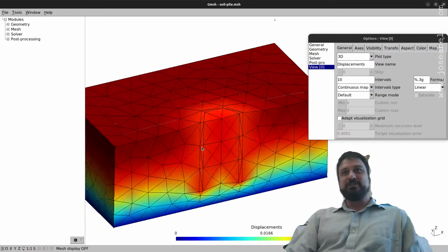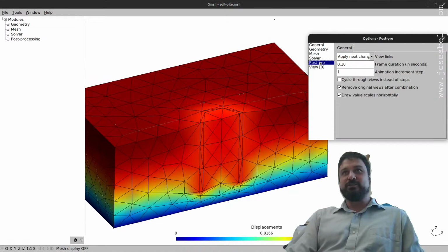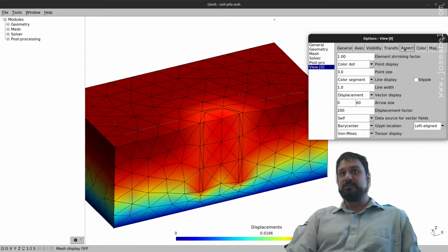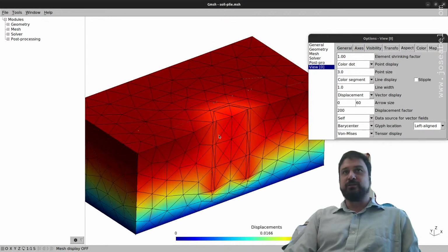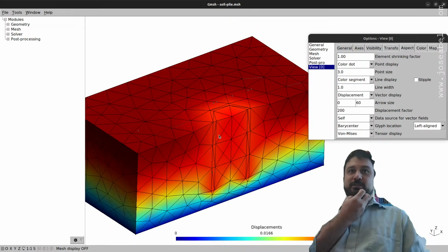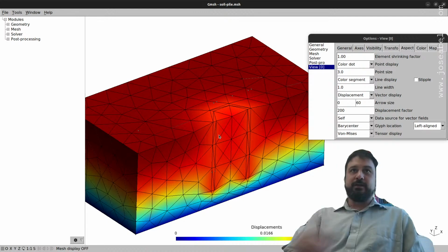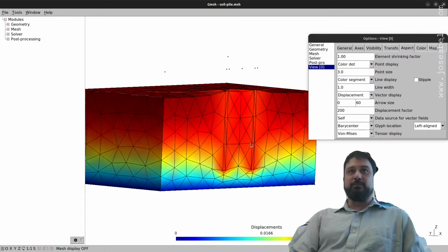Okay, so this is the mesh. This is a high order mesh for this soil pile, but I can't see the pile in high order, so it doesn't look as nice as I'd like. But that's okay. This is looking fine. This is a nice mesh to get started with doing some more stuff. And let's do some more stuff. So let's maybe, to the top elements, I could add a load just to get the pile embedded a little bit more.